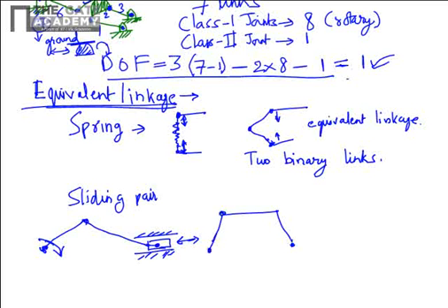The 4-bar chain is a very important kinematic chain which we will consider in much more detail in coming slides. So here there are 4 links joined together by rotary joints, and one link can rotate. If you see the motion of this, you can just visualize the motion of this link in a rotatory fashion. Similarly, this link will also rotate.